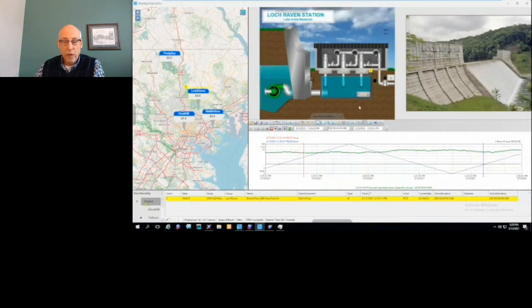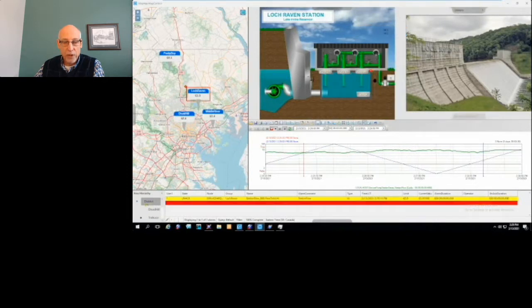In this case, we're going to go change that set point to give that alarm a higher priority. So go change that value here. And then on my graphic, you're going to see that alarm border animation is indeed going to change to red, telling me that there's an alarm condition at a higher priority and gets the operator's attention. It's flashing right now because it's unacknowledged. If I did acknowledge that alarm, it would stop flashing, and if the alarm went away and it was not acknowledged, it'd kind of be a red grid around that device.